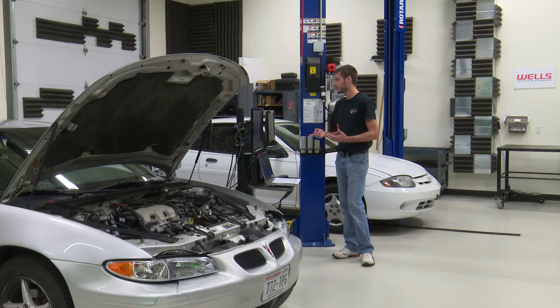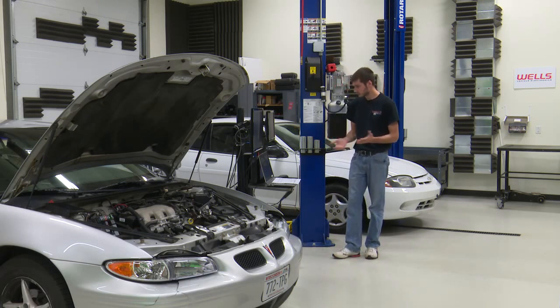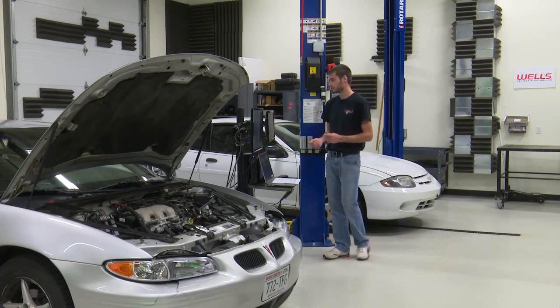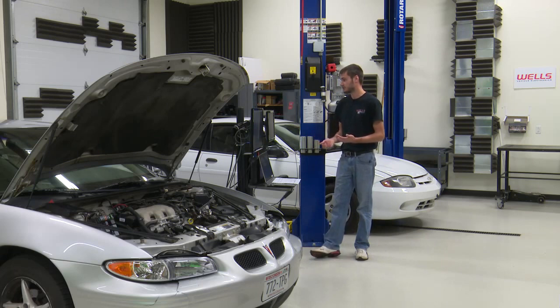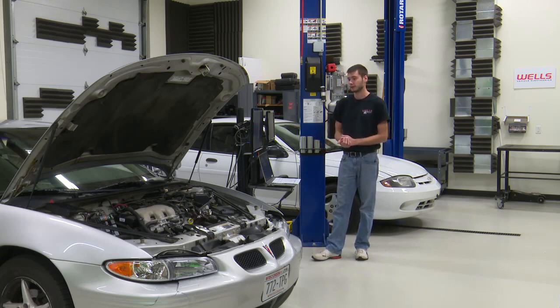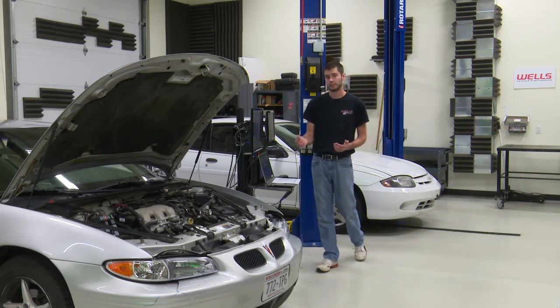What is another time? You could have timing belt issues, timing chain. You had brought up one where the cylinders are washed. Yeah, if the cylinders are washed, you will not see that. Right, you're not building compression in washed cylinders, so it could cause that, and you can prove that out by doing a test like this.